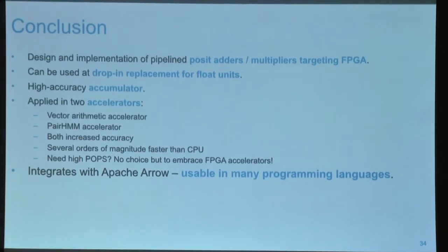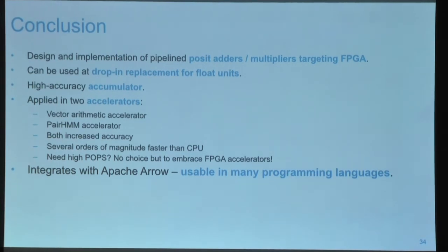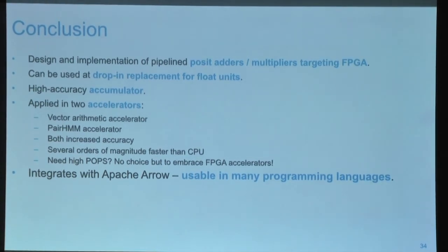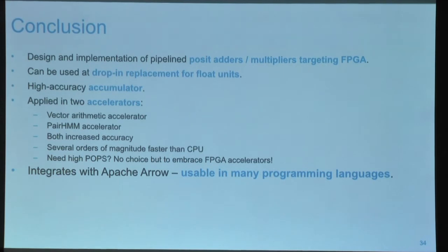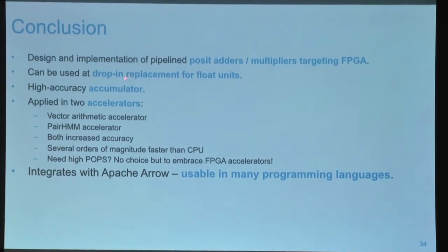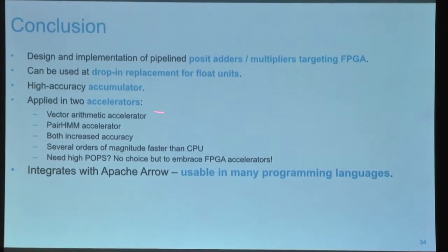posit adders and multipliers targeting FPGA. We can use them as a drop-in replacement for any designs that use float units currently. Again, except when you want to use a quire, you have to do some extra work. So we have a high accuracy accumulator.